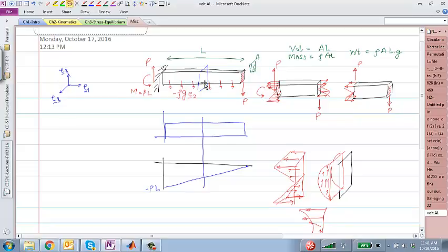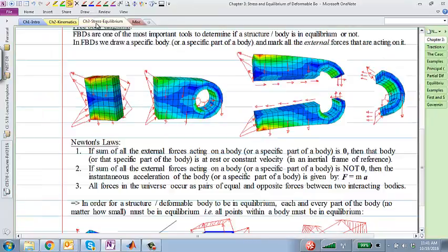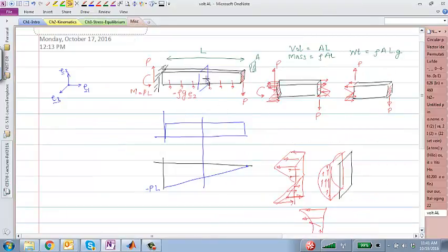But in this particular diagram and in this particular shear force diagram, I'm not taking into account the body forces. But you're right that if I were to take into account those body forces, this value here would be P plus all of that, right? P plus the weight. So you would still have the same sort of distribution, something due to a moment, something due to a shear force.